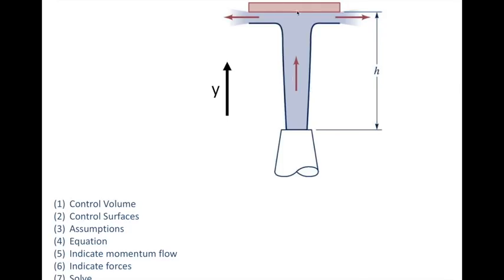So we've got this shooting straight up. I would draw the control volume to capture the water here all the way around. We've got a control surface where it's entering down as it exits the nozzle. We've got it going out horizontally across the edges here. And I believe you're going to want to apply, again, just one component of the momentum equation, and that is in the y direction. That's how I'm specifying the vertical direction here.